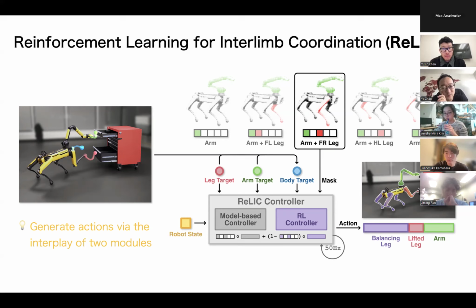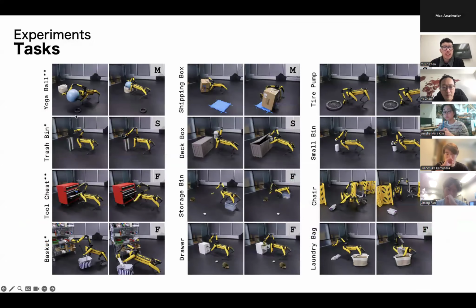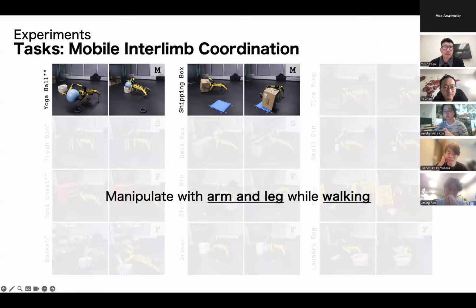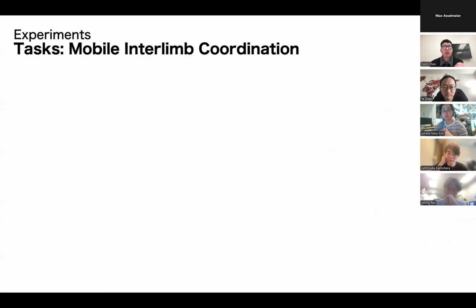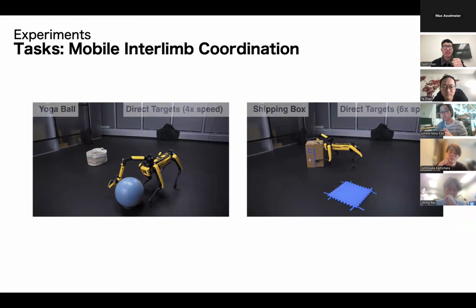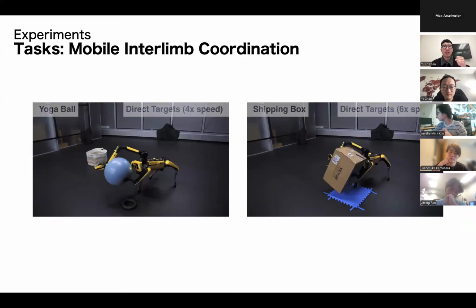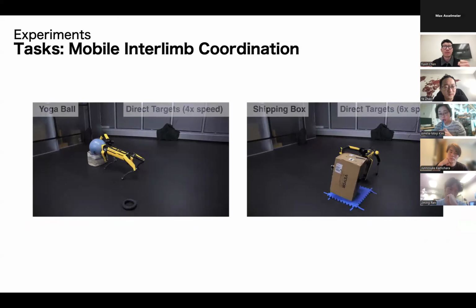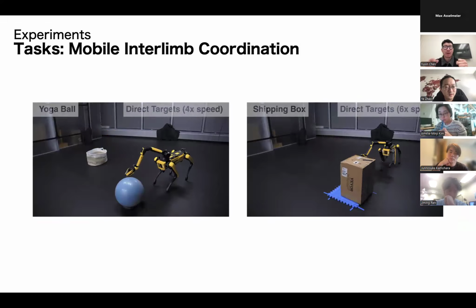I think if you want both good locomotion and stable manipulation, you really need to inject some model-based information into this. In this case, only in the first category do we have bimanual manipulation while walking. Once we hold the object, like during the picking up motion, the robot is just standing there, so there's no vibration from the locomotion side. Once we pick it up, we start moving. So in that case, we try to avoid this kind of more complex problem.